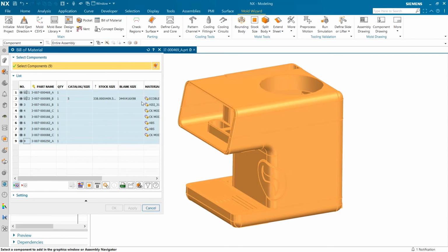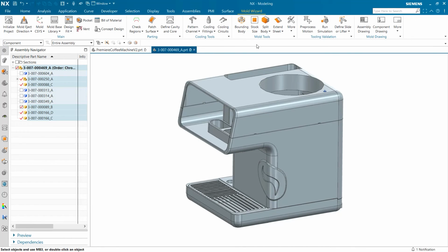In conclusion, in this video, we reviewed the basics of setting up a bill of material for our subassembly. We started by setting the size for our part using the Edit Stock Size command. After that, we filled the rest of our table and created a QR code for the back of the part. And finally, we finished by exporting our data to Excel for use down the line.